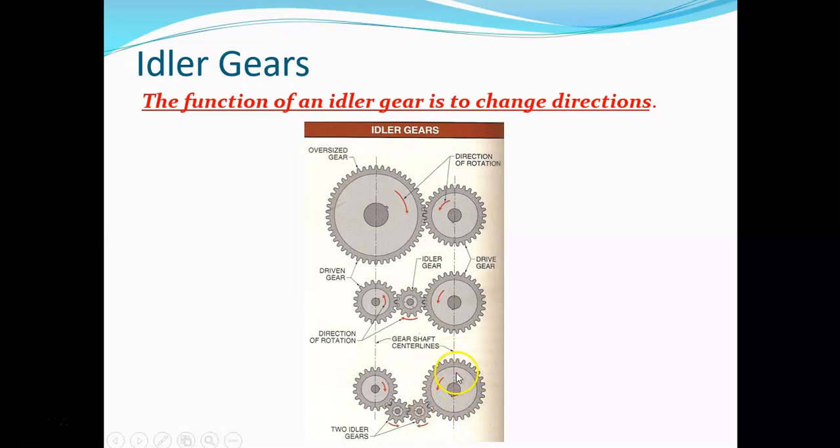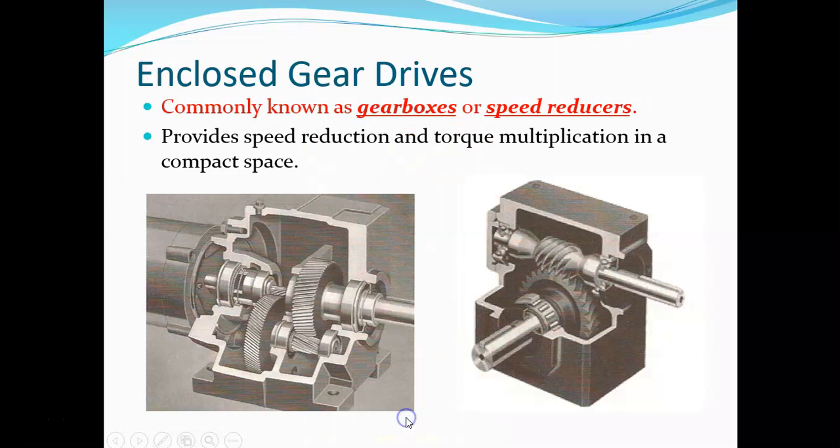So here, just for explanation or demonstration, we've got counterclockwise input going to an idler gear, it's going clockwise. It's going to an idler gear, it's going counterclockwise. And then it's meshed into a gear that is now going, I'm sorry, going clockwise. I'm getting all that mixed up going through them, but there's really no point of having a setup with two idler gears.